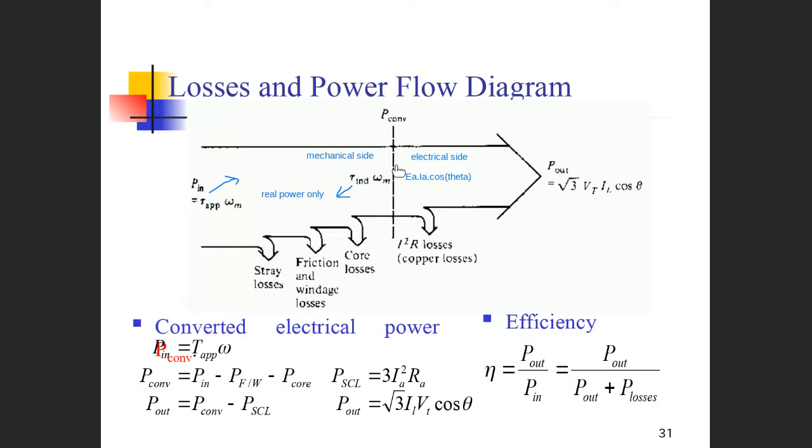No copper losses here. So when the secondary is open, the input mechanical power is just the friction, windage and core losses. So the open circuit test can give the core losses, mechanical losses, and stray losses of generators. In practice, we can do the open circuit test like this, so that we can get the generator's open circuit losses. The copper losses, of course, depend on loading levels. If the loading level is higher, copper loss is bigger. If the loading level is smaller, copper loss is smaller.